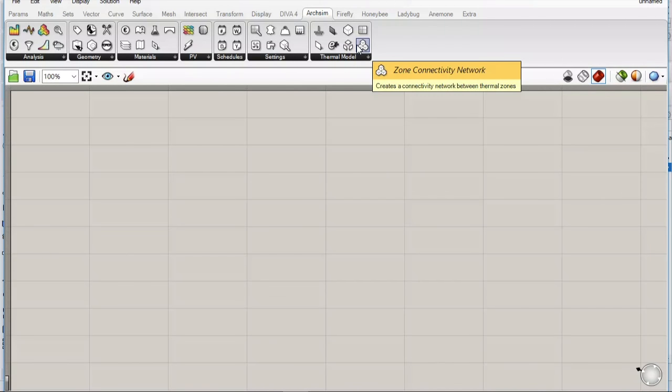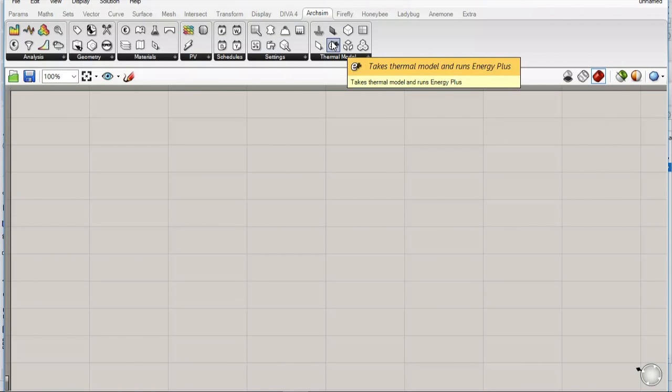The starting point, if you remember, with ARCHSIM simulations, is we need to bring our Rhino form into the Grasshopper domain. So all of these processes that we're going to undertake in Grasshopper actually know which geometry we're referring to. And we do that with these ARCHSIM components, and this goes back to why I've represented the body, glazing, and shading as different layers: in ARCHSIM we also treat these as 3 independent components when we're assembling our ARCHSIM model.